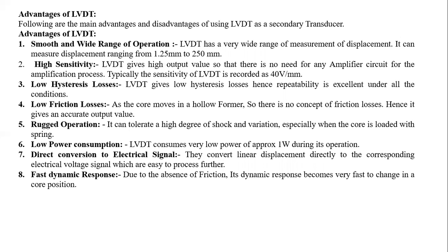Rugged operation. It can tolerate a high degree of shock and vibration, especially when the core is located with a spring. Low power consumption. The LVDT consumes very low power, approximately 1 watt during its operation. Direct conversion to electrical signal.